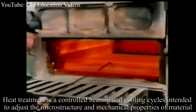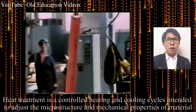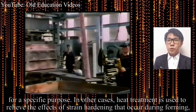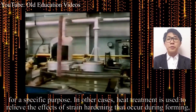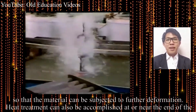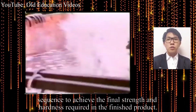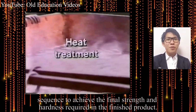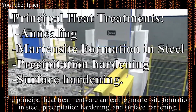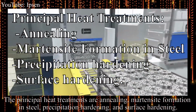Heat treatment is a controlled heating and cooling cycle intended to adjust the microstructures and mechanical properties of material for a specific purpose. In other cases, heat treatment is used to relieve the effect of strain hardening that occurs during forming, so that the material can be subjected to further deformation. Heat treatment can also be accomplished at or near the end of the sequence to achieve the final strength and hardness required in the finished product. The principal heat treatments are annealing, martensite formation in steel, precipitation hardening, and surface hardening.